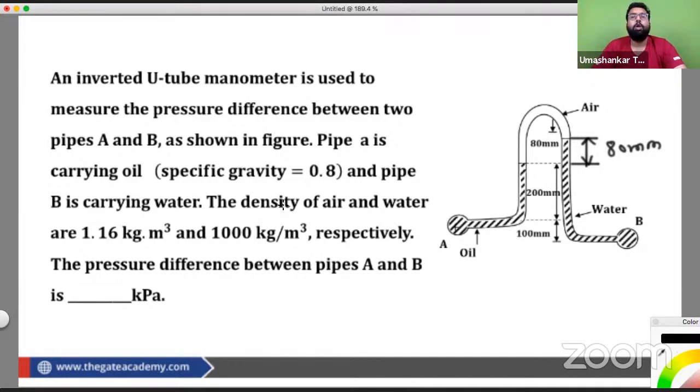Okay, so I'll do it. When you see this kind of question in your examination, I hope it is very easy to recognize that, sir, this is a question of manometer. If it is a question of manometer, what we should do is change everything to water. If we are moving upwards, we should subtract. If we are moving downward, we must add, right?